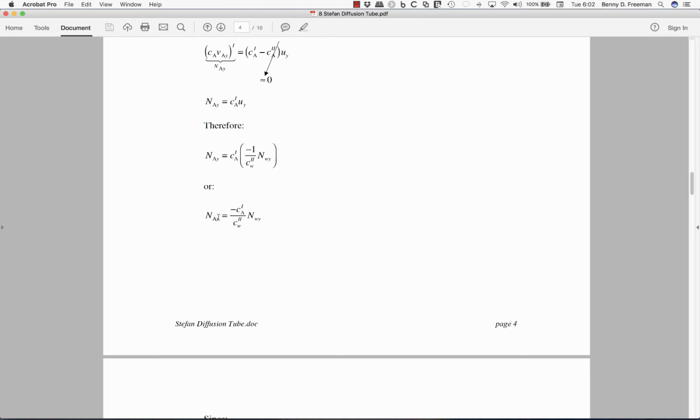All the air has to do is take the place of liquid that's evaporated. The water is expanded by more than 1,000 times on going from the liquid to the gas phase, and so its flux in the gas phase has to be way greater than that of the air, which is just displacing the liquid in this tube.